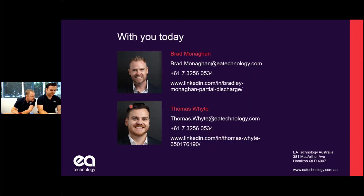Okay, TEV can be used for cable head monitoring. The answer to that question is yes. Can you use the TEV technique to monitor for cable head PD? The best way to do it is you'll have your cable head termination up on the pole. You'll have your trifurcation up the very top. The cable will come down the pole. It'll usually sit behind some cable guards, or maybe it doesn't.